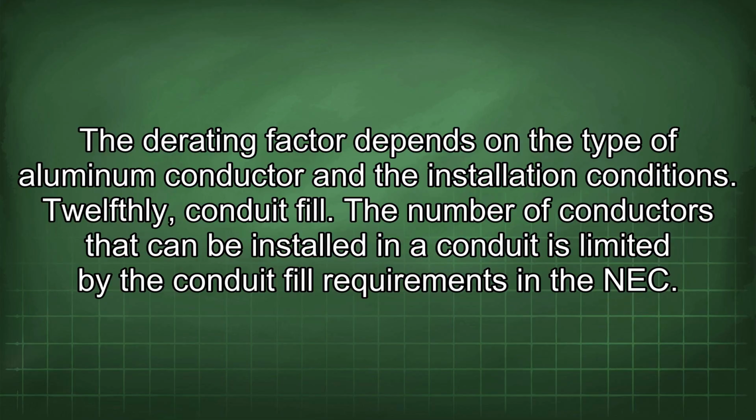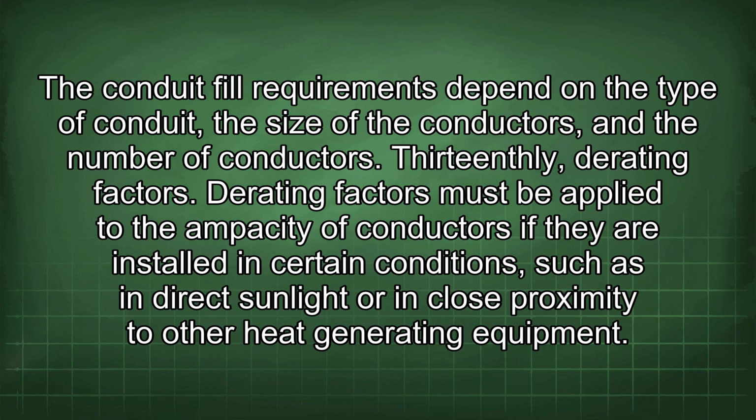12thly, conduit fill. The number of conductors that can be installed in a conduit is limited by the conduit fill requirements in the NEC. The conduit fill requirements depend on the type of conduit, the size of the conductors, and the number of conductors. 13thly, derating factors.